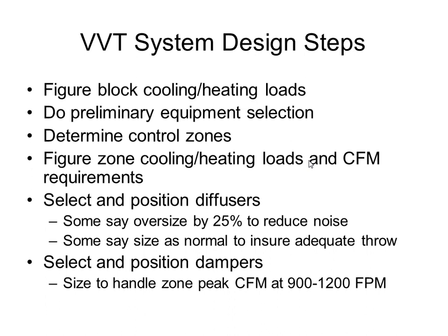Once we have our loads and CFMs for the zones, we want to pick our diffusers. Now that you have the CFMs, you know what diffusers you should use. A lot of people say oversize them by 25% for noise. I like to say use the normal size based on the CFM so you get adequate throw and dispersion into the space, but everyone has their own rules of thumb here, so probably won't hurt yourself by oversizing by 25%, but again, you don't want any dumping. You want proper dispersion of air.